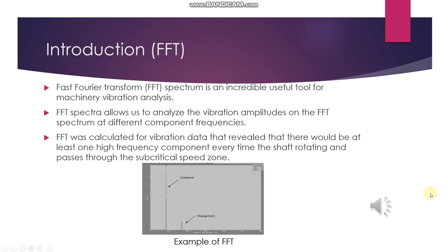For the next slide, it is about the introduction of FFT. Okay, first point, the fast Fourier transform, also known as the FFT spectrum, is an incredibly useful tool for machinery vibration analysis. As we can see, in industry, most machines have at least one shaft that will commonly face faults. With the help of this tool, it is easy to identify the shaft problem.